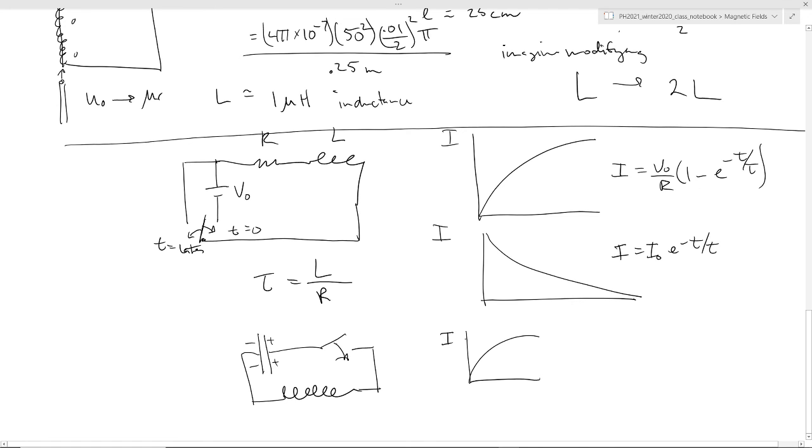sorry, let me put it this way. This is the inductor behavior, and with the capacitor, it goes like this. Sorry. You get what I'm getting at here. It goes like this, and so you have sort of a competition between these effects, and what this causes is an oscillator. So the current will flop back and forth between these two energy storage elements, and it's a way to make an oscillator.